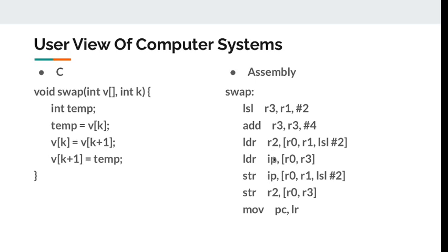So we select some registers in the CPU, and you can use those registers to save the memory while the CPU is working. And after that you can return from this subroutine, and you can move the program counter back to where it was before, and you just did the swap operation.